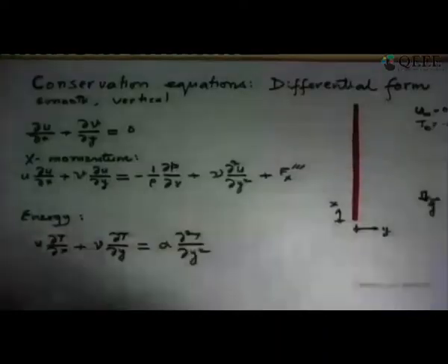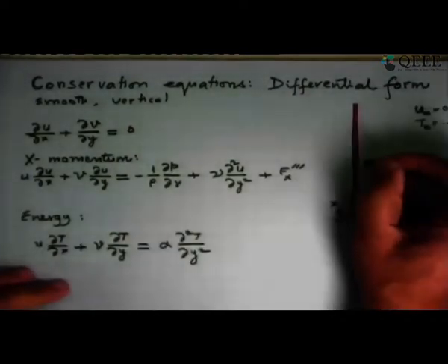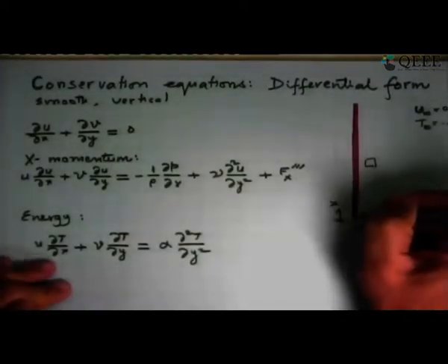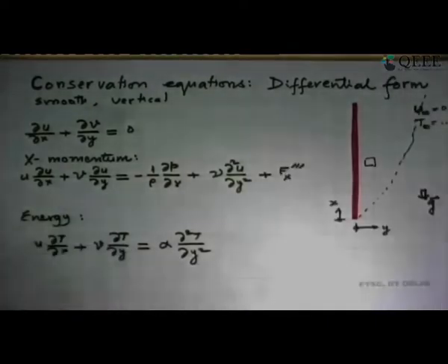Okay, so now having looked at how the boundary layers develop, the hydrodynamic boundary layer and the thermal boundary layer, we say, well, let's write the equations for the boundary layer. And we only do the differential form of these equations, where the surface is heated and we are going to consider an element over there, and as we have seen, there is a thermal boundary layer that builds up like that, and very close to that is also the hydrodynamic boundary layer.